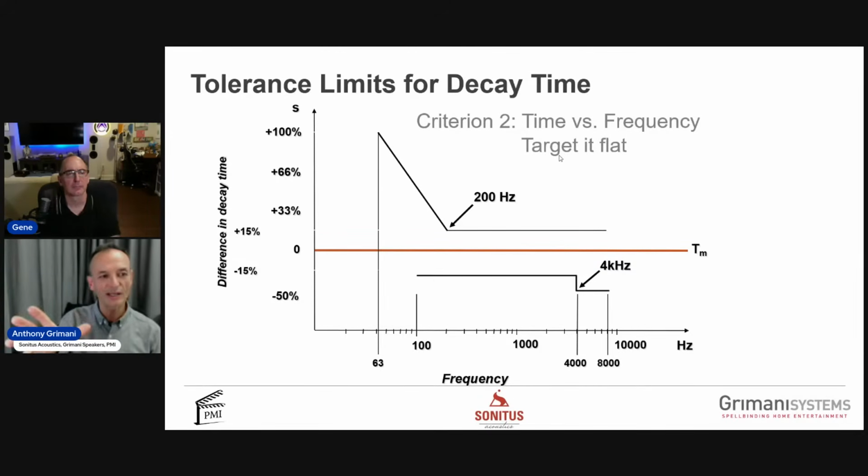If you could instantly go to the Library of Congress and look at all the books on room acoustics and what people like for decay times and how you build rooms with good acoustics, they would tell you first you want to have this decay time, and then tell you that that decay time needs to be as smooth across frequency as possible. So let's say we're talking about this 450 square foot room that should have a decay time of, whatever I said, 0.32 seconds. You would want that at 1,000 hertz, at 4,000 hertz, at 10 kilohertz, at 63 hertz.